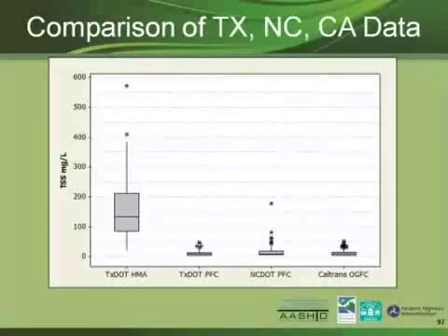so a huge difference for sites that are right next to each other. And roughly coincident, Bill Hunt in North Carolina started a project monitoring the improvement in runoff from vegetated shoulders, exactly what we were doing before, actually. He didn't realize that the pavement was PFC, and he got out there and started monitoring. All of a sudden, the runoff at the edge of the road was super clean, and of course, he got no improvement after it went through the grassy area.